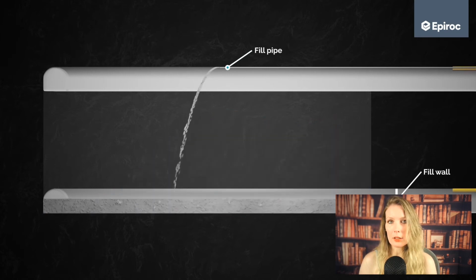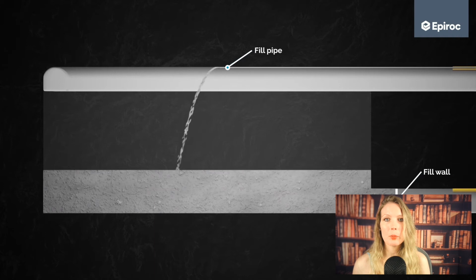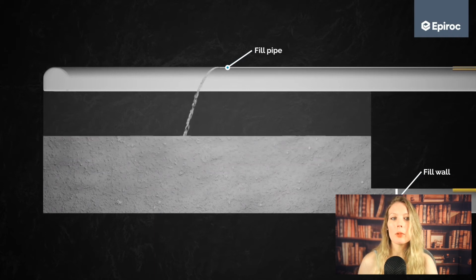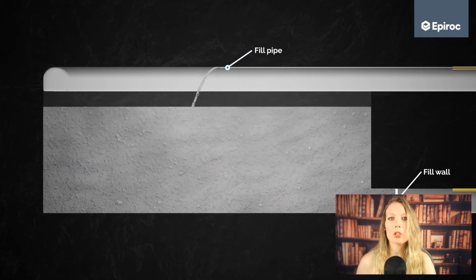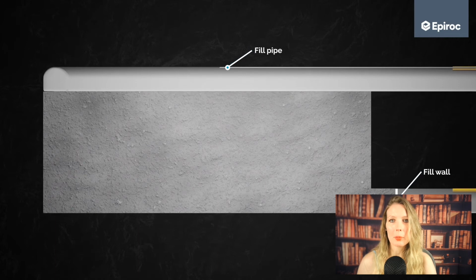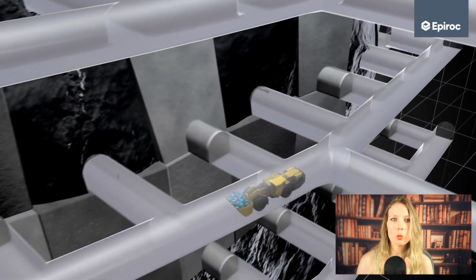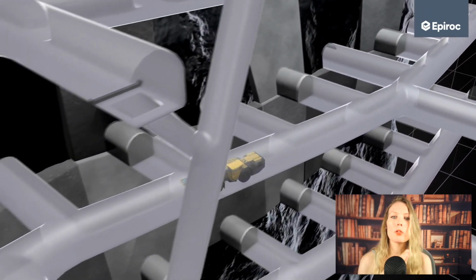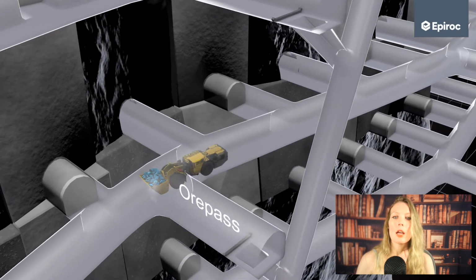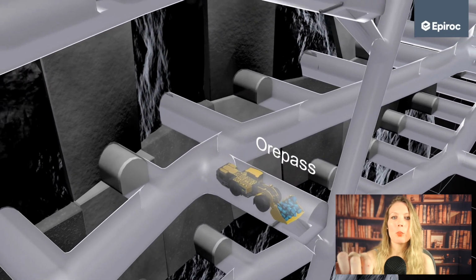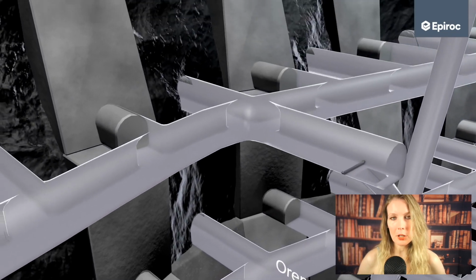And the final factor is rock mass stability, which focuses on keeping excavation sequence control to lower the risk of collapses. In cases where stopes are adjacent to each other, removing support pillars too early can lead to ground movement affecting both safety and ore recovery.